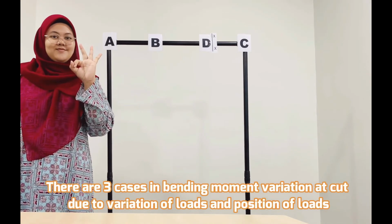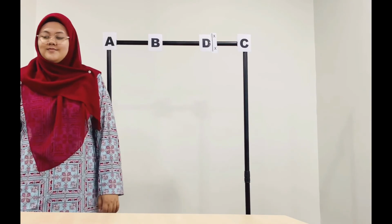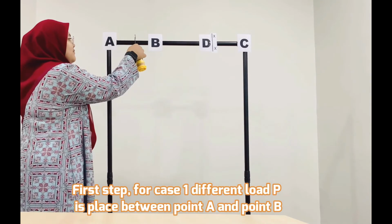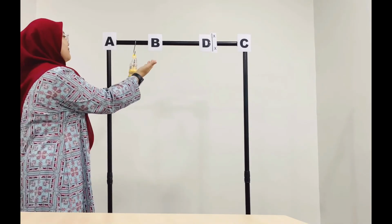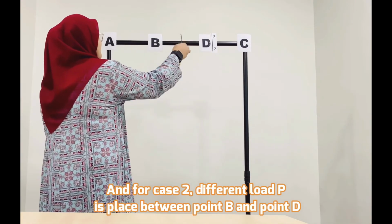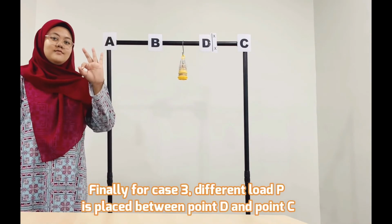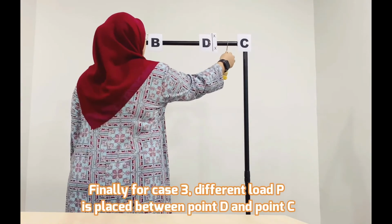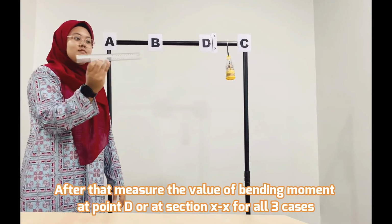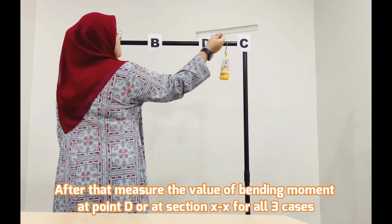Hi! There are 3 cases in bending moment variation at cut due to variation of load and position of load. First step, for case 1, a different load P is placed between point A and point B. For case 2, a different load P is placed between point B and point D. Finally, for case 3, a different load P is placed between point D and point C. After that, measure the value of bending moment at point D or at section XX for all 3 cases.